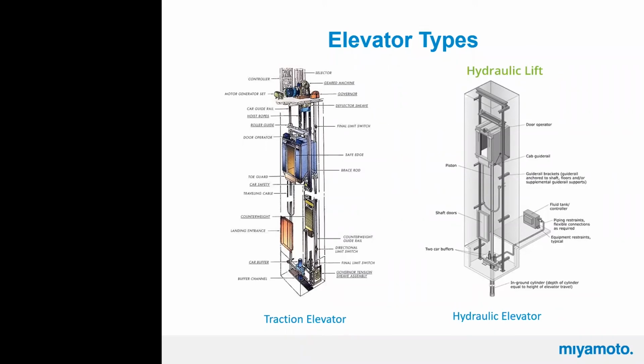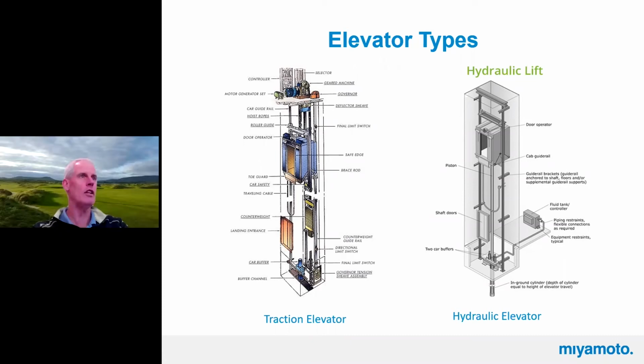And like I said, because each of those pieces of equipment usually drops something down into the shaft, they have a bunch of holes and they never line up like it's a straight perfect beam. And the deflection criteria is pretty large, and the reactions from those things, not so much for the weight of the machines, but the reactions for the operations are very large.